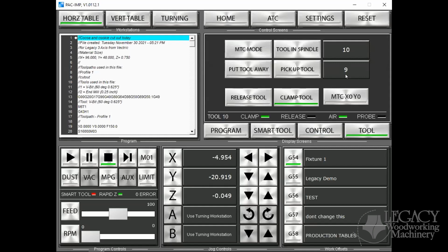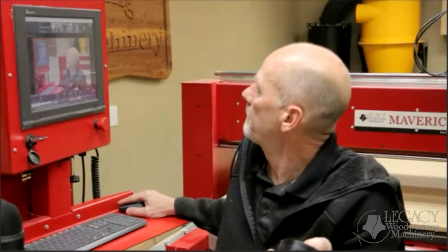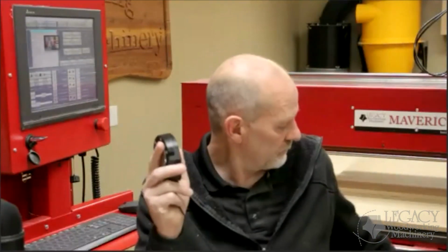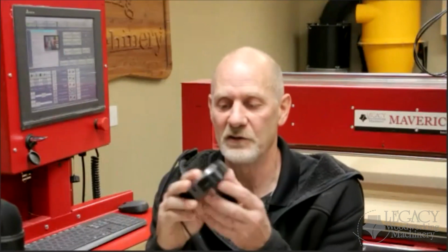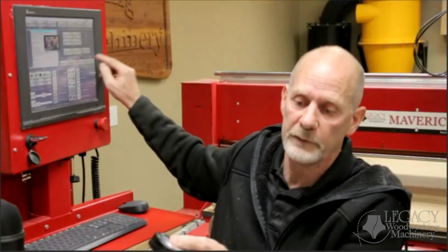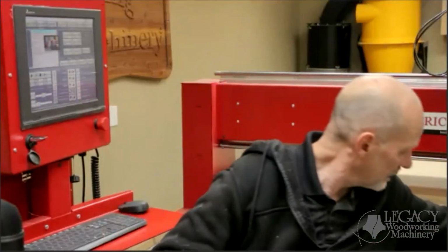So this is a really good practice. Okay, this is an excellent practice when you're using your machine, because if you tripped on that cable or shorted it out, or if it wasn't plugged in or something, and you try to touch off without it functioning, then you'll crash. You could damage it. So it's real good practice before you ever do a Smart Tool setup. Just take this pad and hit it, and you're going to see the little light come on the screen right up here. Then you know it's good, and you're good to go.